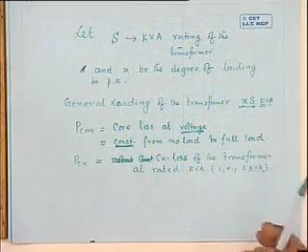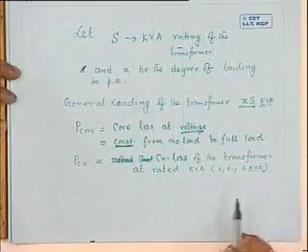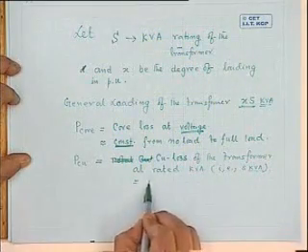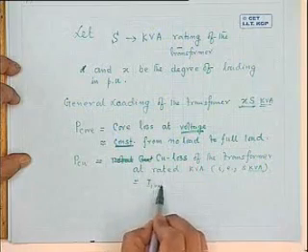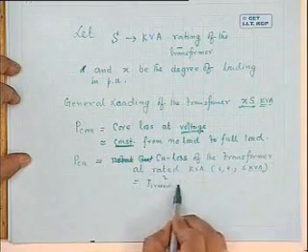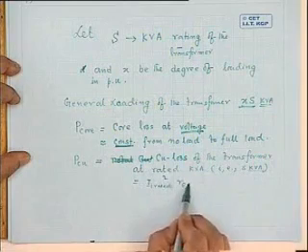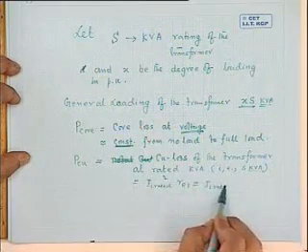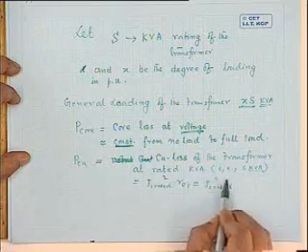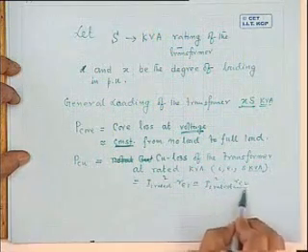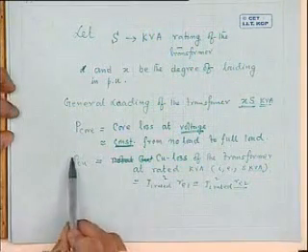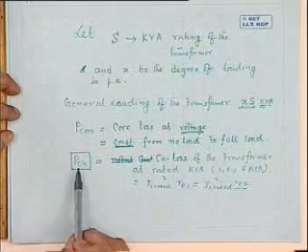And for that you need not know how much of R_e1 is R1 and R2 to calculate efficiency, etc. So this copper loss at rated kVA will be equal to I1 rated current squared into R_e1, and this will be the same as I2 rated secondary current squared into R_e2. All these things will be there.